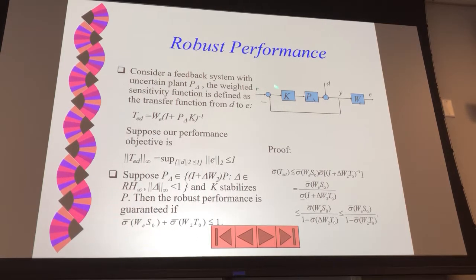So you could do T_ER as well. That's called a closed loop transfer function. And again, this is an LTI system. When I consider my E due to D, I consider R to be 0. You can see from here, T_ED is the closed loop transfer function from D to E. We write this complementary sensitivity transfer function matrix T, with subscript E and D. That's the signal going from right.